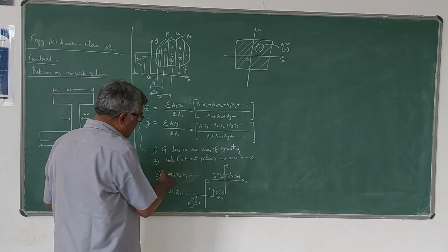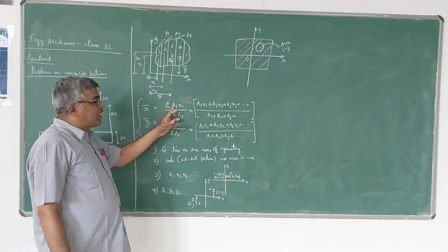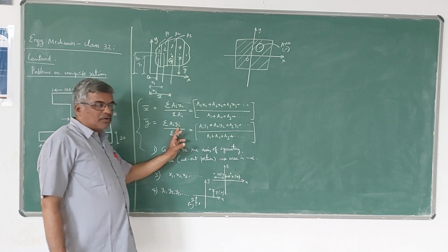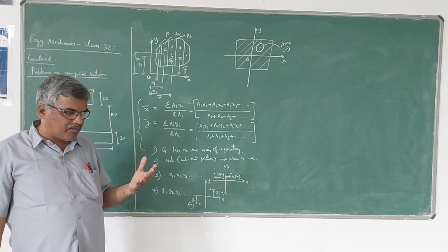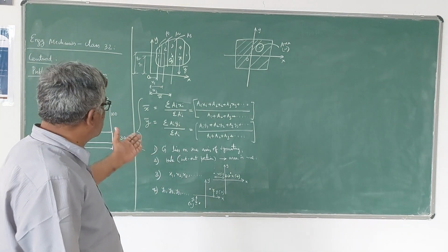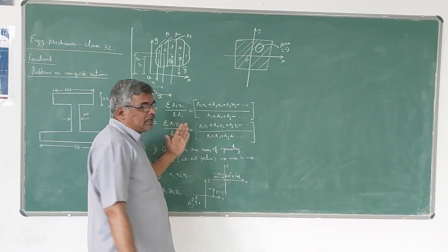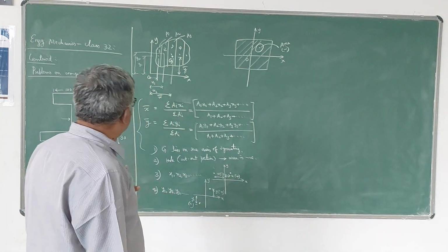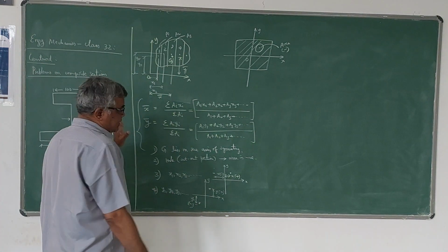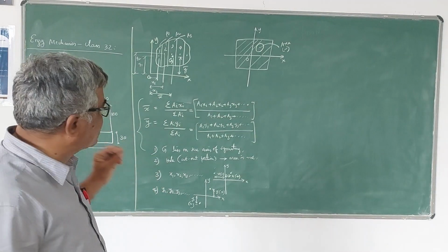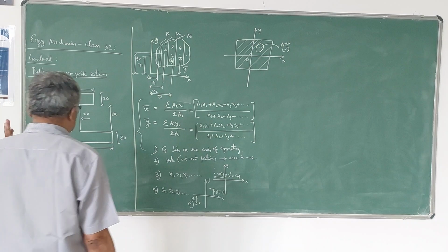Once you get those values, here A can be positive or negative, x can be positive or negative, y can be positive or negative. So once you know all those values, then you can use these two formulae to find the location of the centroid G of the composite section from the y-axis and x-axis. So these are the general guidelines to locate the centroid of a composite section.